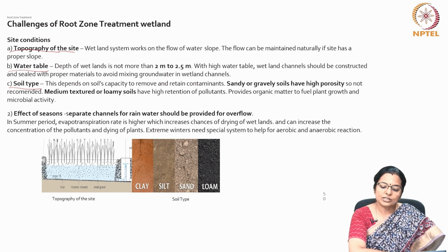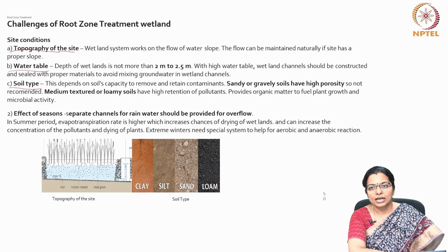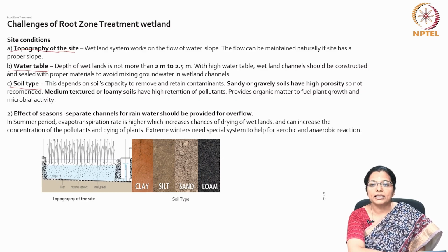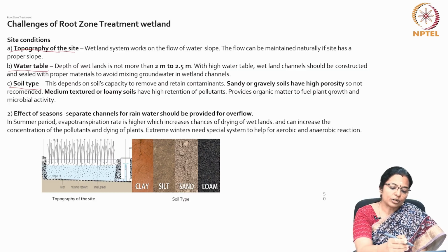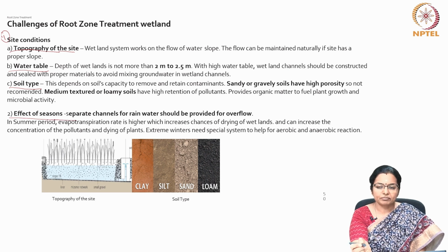This depends on the soil's capacity to remove and retain contaminants. Sandy or gravel based soils have high porosity, so it is not recommended. Medium textured or loamy soils have high retention of pollutants and they provide the organic matter to fuel plant growth and microbial activity. Then another important criterion is the effect of seasons.